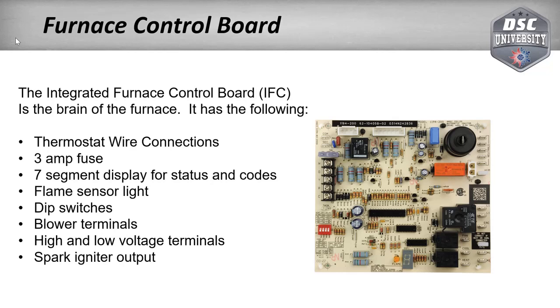In the furnace, we have an electronic control board. It's called an integrated furnace control. And Rheem started using these back in 1992 when Rheem went to the 34-inch tall furnace. Before that, they used some circuit boards, but the circuit boards didn't control everything. In 1992, they took all the different relays and a fan center and a fan and limit control. They took all those old mechanical parts and combined them all into one electronic control board just to simplify things.